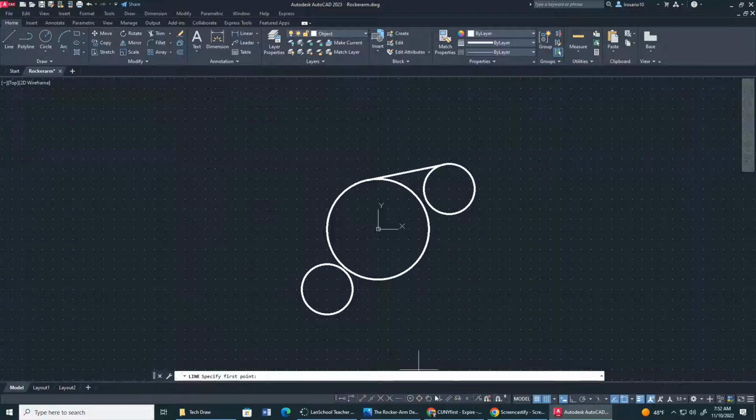So again, that's line, tangent snap. I'm going to make sure the circle with the line comes up, and then I'm going to do tangent snap again, and there it goes, okay? I'm going to press escape. So again, line, tangent snap, tangent snap again. You have to press tangent snap twice, right? Now, this is so far coming along pretty well. Let's continue.